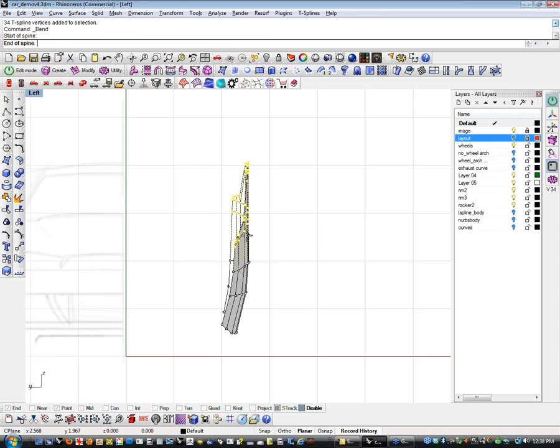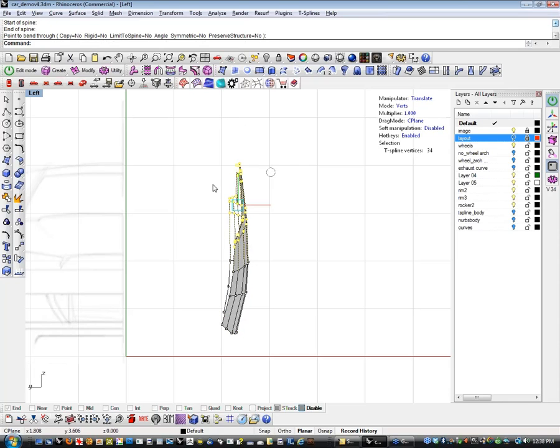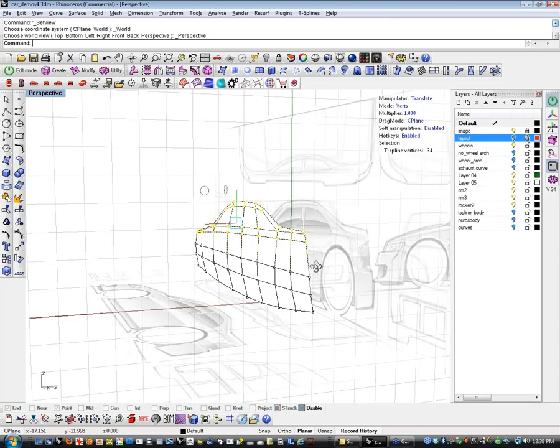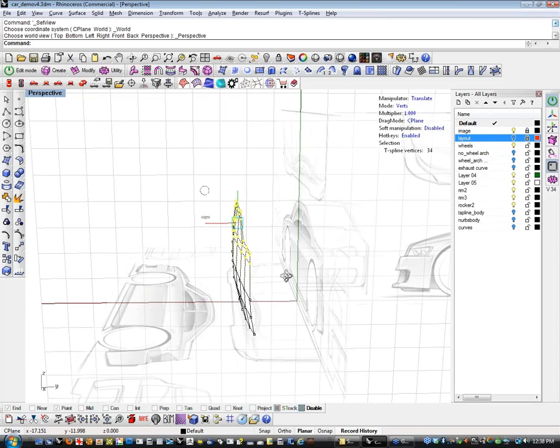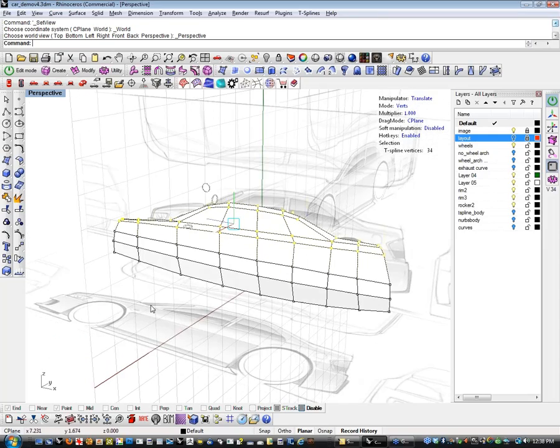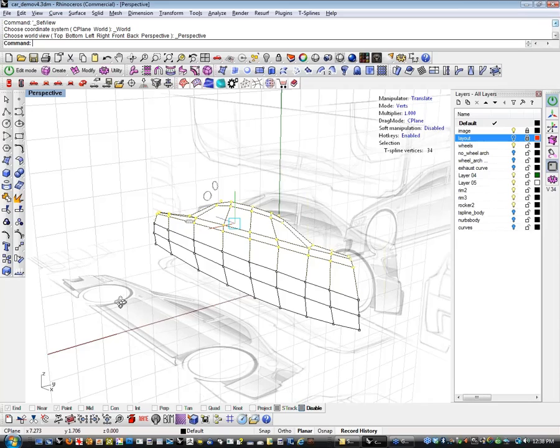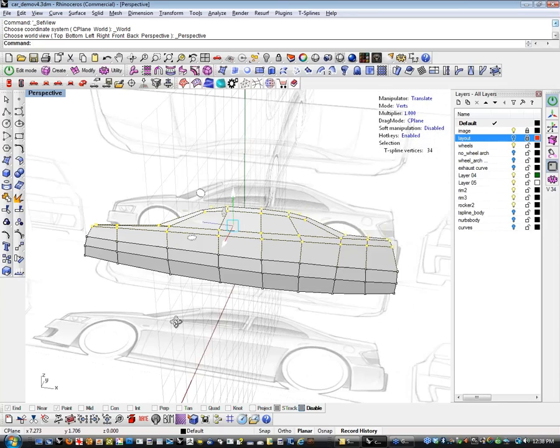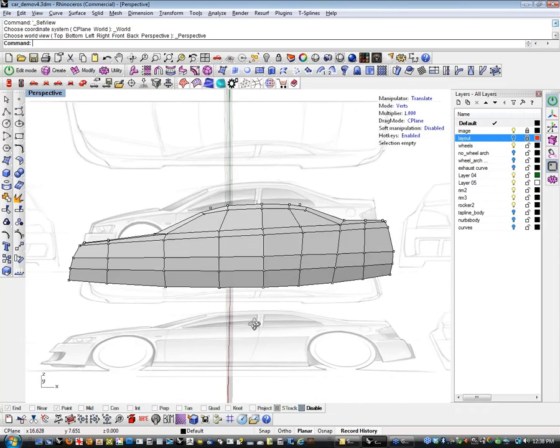Is everybody appreciating how awesome this is? Because this is awesome. Because I can do this all day until everybody's happy. All right, so we've just used the bend tool to place all these points. We've introduced zero inflection to the model because they were all mathematically placed. And this thing is starting to take shape as a car.